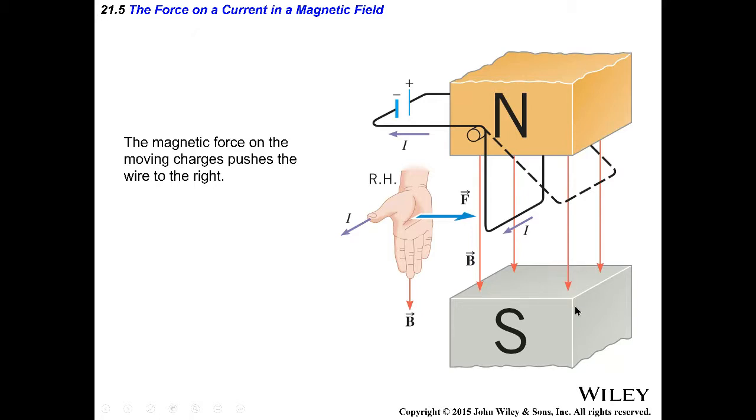As it is going up this way, the current flows in this direction. But when it is the other side, because this is a loop, the current flips around. Why? Because my magnetic field is still this direction, but now you're flipping it around, and that's why you get an AC current. We will come to that when we come to the chapter on Faraday's law.